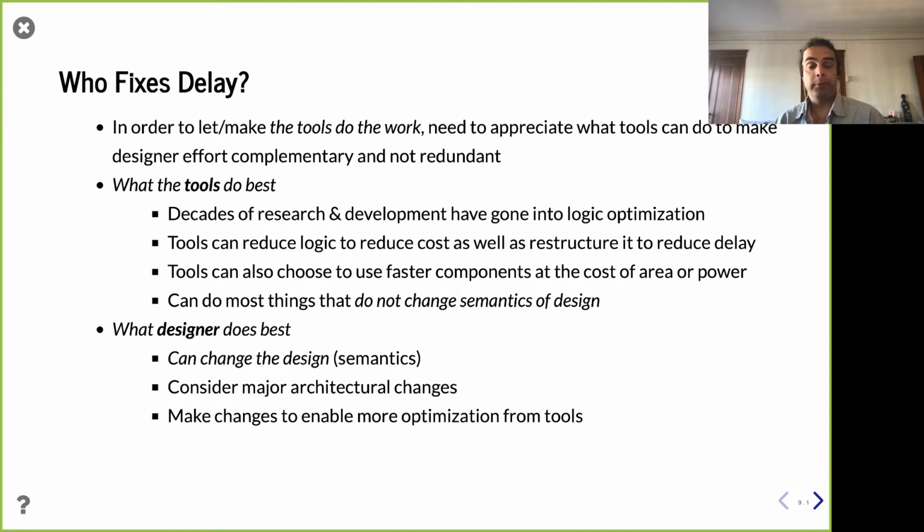There are cases in software programming where optimizing compilers can do amazing things. However, inadvertently you might declare things in a way in your code that makes it impossible, especially in a language like C, for example, where maybe you have those weak types. It's unable to reason about your pointers to allow for vectorization. A similar kind of thing happens in hardware, right? So, okay, tools can really optimize logic really well, as long as you're not asking them to change the semantics. They can do that very, very well.